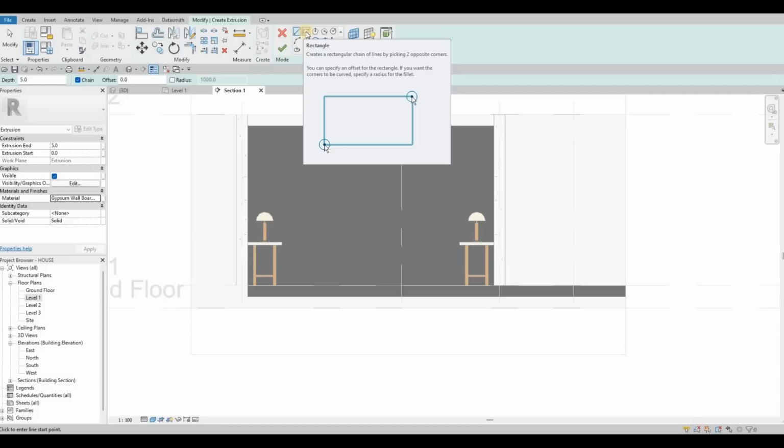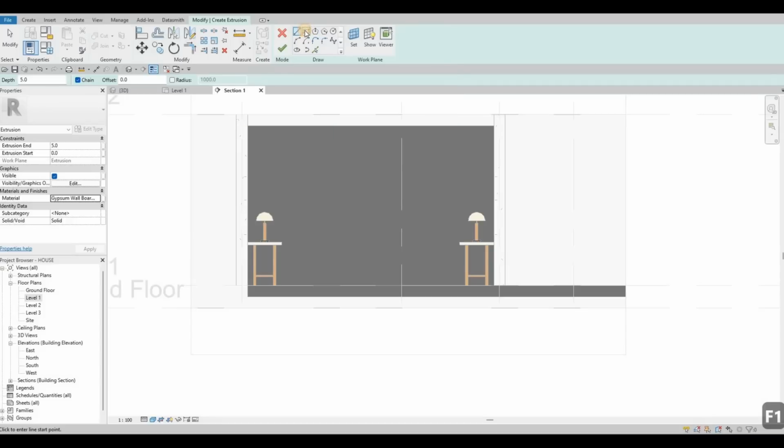What I'm gonna create is just a box first. So now we're going to select the rectangle, and I'm going to add the rectangle right here, right in the middle. So I'm just estimating the size at the moment, around 1400 by 1700. And then we're going to offset this 150 probably or more.